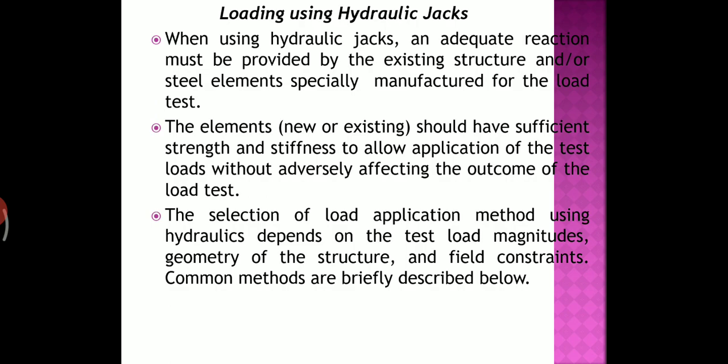Yes, the elements, new or existing, should have sufficient strength and stiffness to allow application of the test loads without adversely affecting the outcome of the load test. So while using jacks, in order to work the jack, the reaction force is to be given. That reaction is being taken from the existing structure or new element, so that one should be very strong.